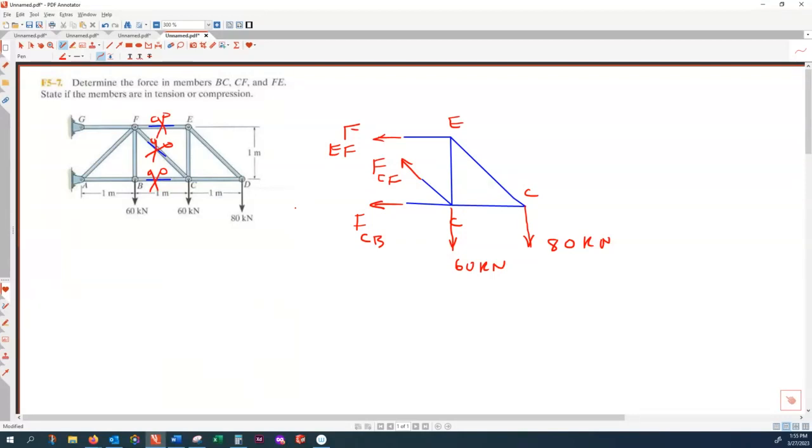So the question, is this free body diagram solvable? How many conditions, how many unknowns? Three conditions, the forces are not concurrent. It has three useful equations and three unknowns. All right, so this problem is solvable. And can you suggest the best condition to apply here? Rotation at C. Yes, rotation at C is a good option.